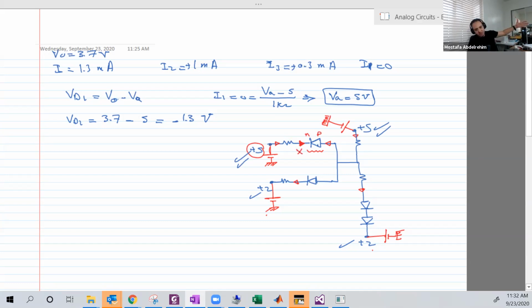Of course, if it's a Zener diode, if you remember the Zener diode, or a normal diode in breakdown, yes. But for our analysis here, usually we assume that no breakdown will occur. So this battery here cannot charge other batteries because there is a diode in between, with its terminal closer to the positive terminal of the battery.